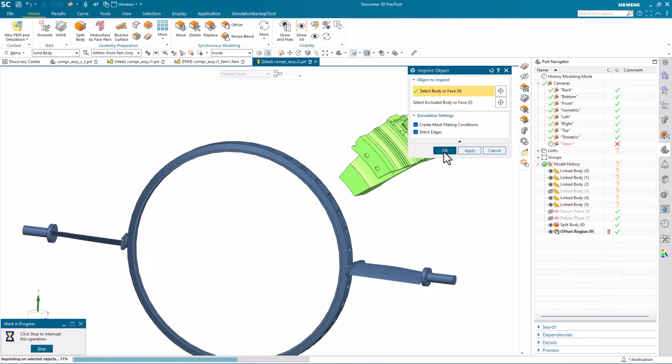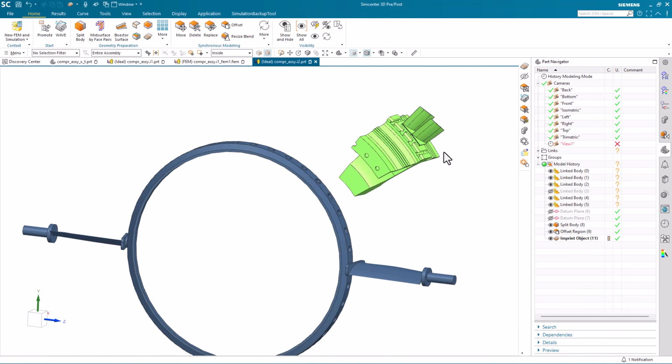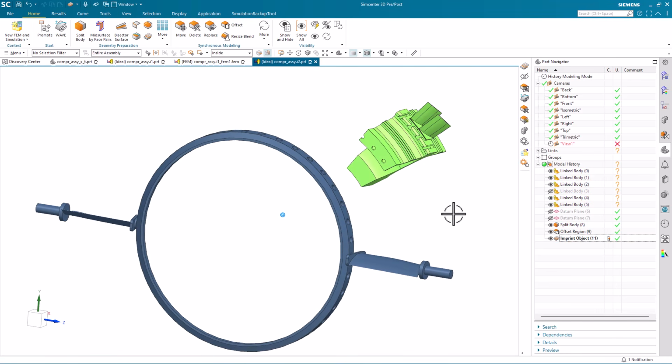And this content that's being generated by this CAD feature is going to be consumed during our FEM creation, when we take our geometry from our CAD to our FEM. So that's a really handy feature. It was added a couple releases ago to our idealized part and geometry operators within the pre-post application.